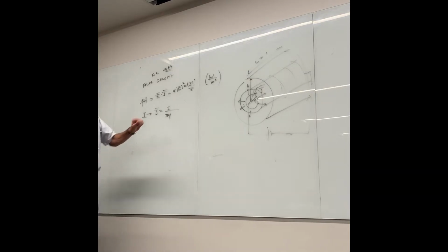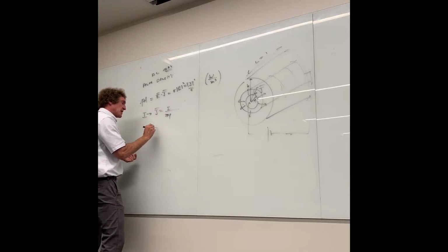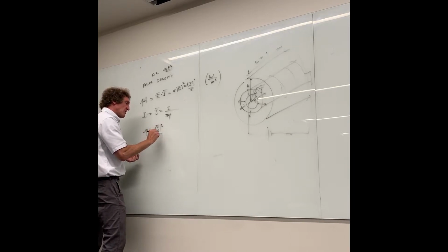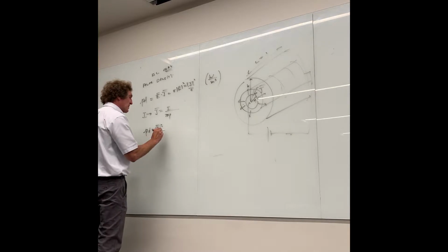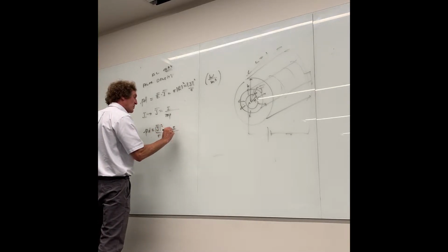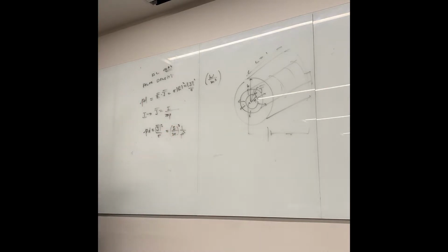Now, power density is J squared over sigma, right? So without doing the E calculation, now I can get the power density, and I know that's the magnitude of J squared divided by sigma. Power density is not a vector, it's a scalar. So that would be I over 2 pi squared divided by 1 over rho squared. Agreed? And the units would be watts per meter squared, correct, class?